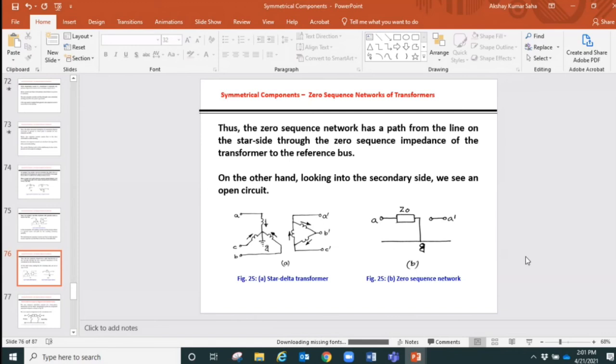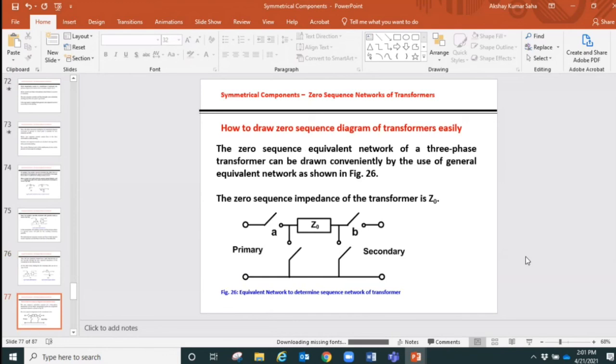So for that, it's very difficult for us to remember and analyze when we're drawing these reactance diagrams, and it takes time. So what was done by people, the scientists or engineers, they made it simple for us. They said, we know that we can represent a transformer by primary and secondary winding and an impedance between them. And we don't need to remember that primary winding and secondary winding impedances separately. If you remember when we are talking about the per unit, because it becomes only one impedance.